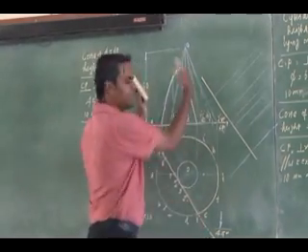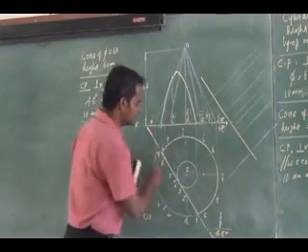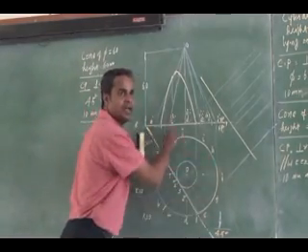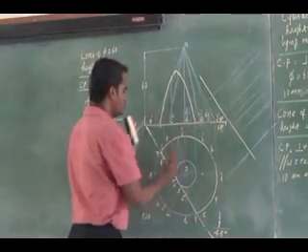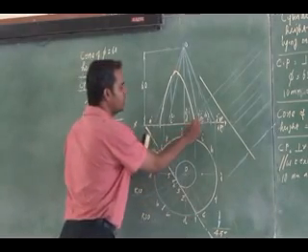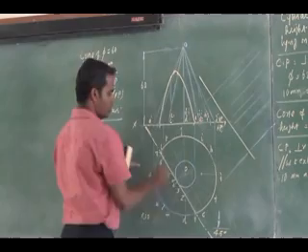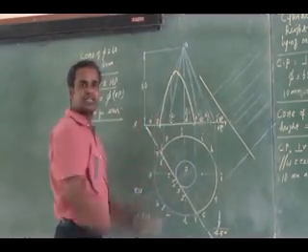This should be projected to the front view to get the sectional front view. So which is the retained portion? This is going to be my retained top view. Then these cutting points are projected. You see here, 1 and 7 on the base. 1 is projected to the front view here. This is my cutting point 1. So 7 is on base, it is projected.